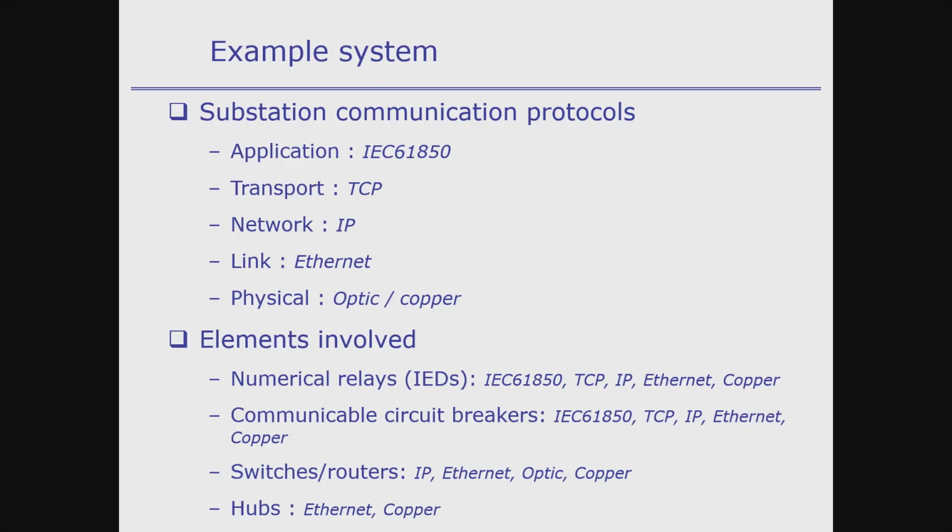Yeah, so in client server communication, an example is you are sending a fault record file. Let's say a fault had happened, and your IED recorded the data for, let's say, 6 cycles, right? That's a huge amount of data, right? And then you transfer it using client server. Whereas in sampled value, you are sampling a voltage.